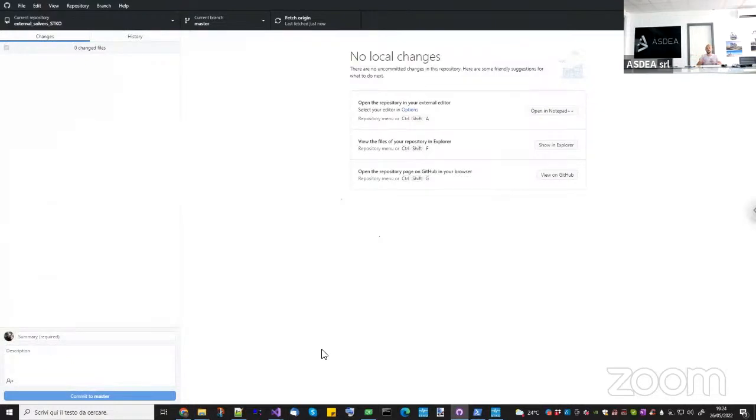Now it is quite complicated, I understand. As I said before, if you're interested in extending the STKO library, the first thing that you need to do is to understand how GitHub works, then how the PyMPC library works, which is the extension of STKO to Python. And then you need to start following this webinar and the next webinars we'll be doing on this topic. It is quite complicated, but if you are interested in extending the Python in STKO or creating your own automation, this one is the starting point.